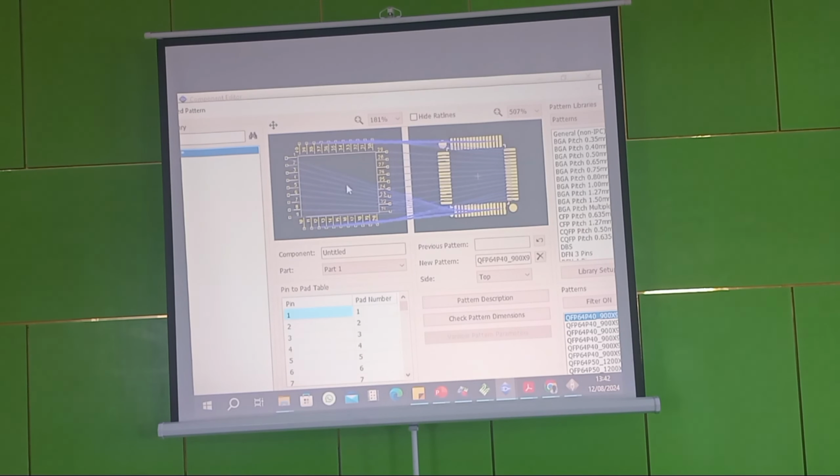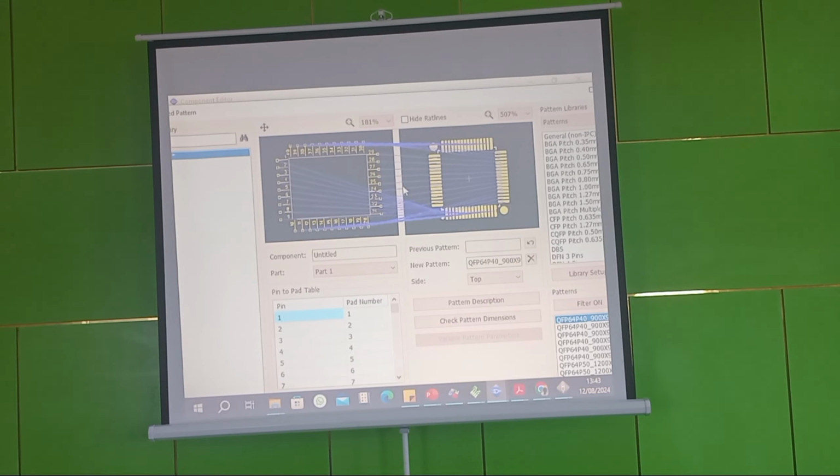Yeah, so that's it. But at the end of the day, the nature of this component, it will give an error that your component graphical symbol does not match. It won't give you the error here, but once you place it on your PCB design, that's when it will start giving error. This software has something we call DRC, design rule check, to check any errors.